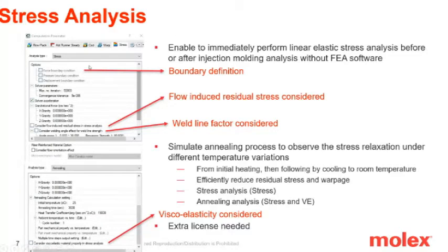So you can define the boundary conditions, the force boundary condition, the pressure, or the displacement. And also, if you run the injection molding simulation, you can include the flow-induced residual stress. Also, if you have the data for the WLF factor, you can apply it here. It gives you some options to do the stress analysis. I think this is convenient to use.